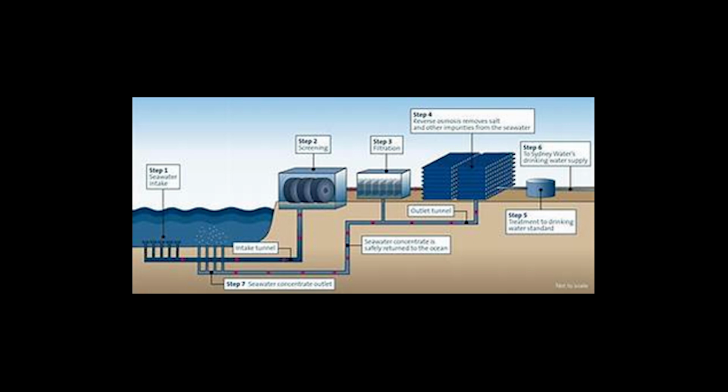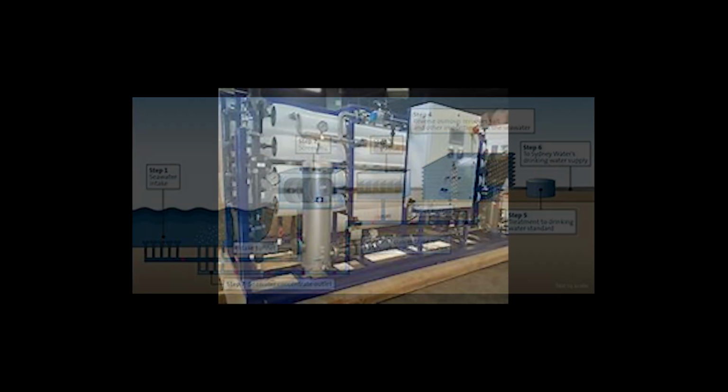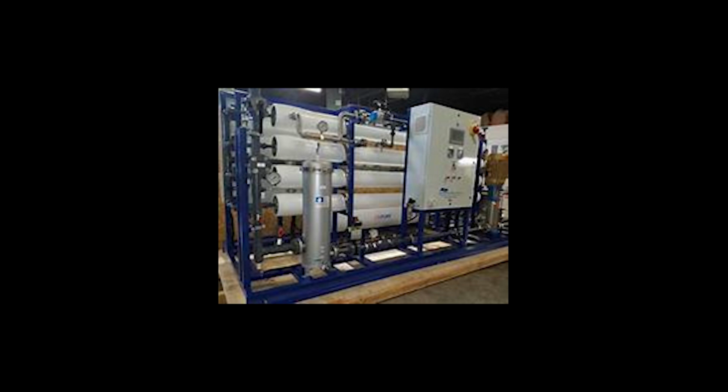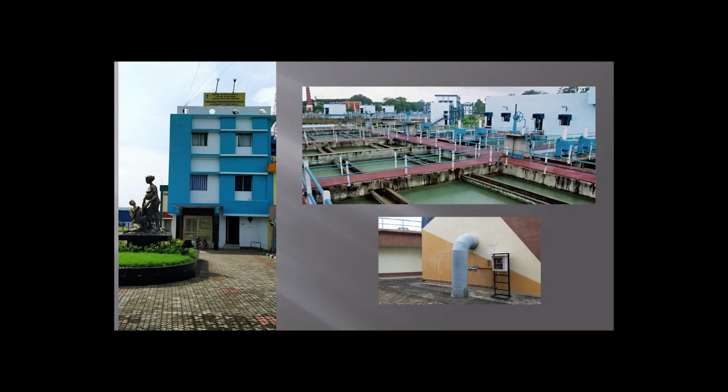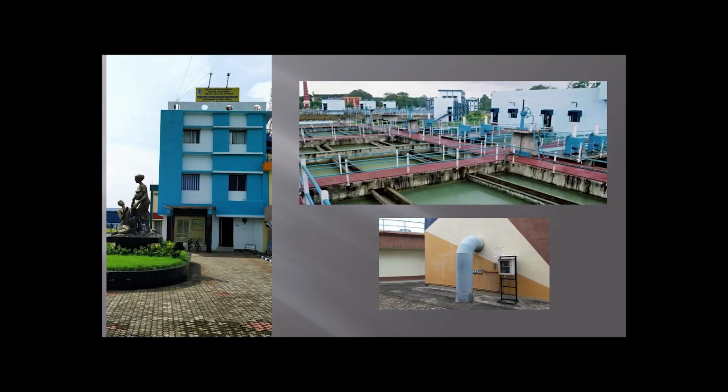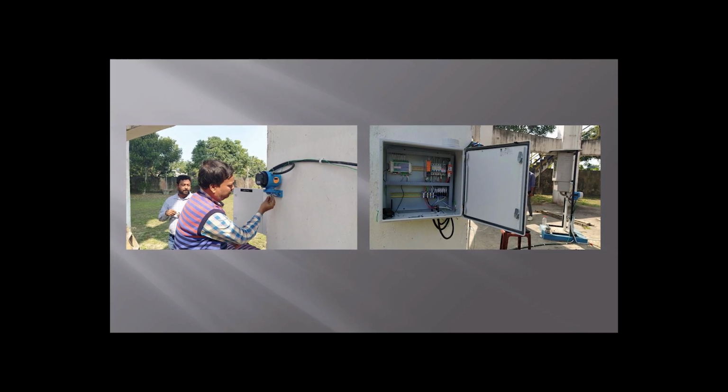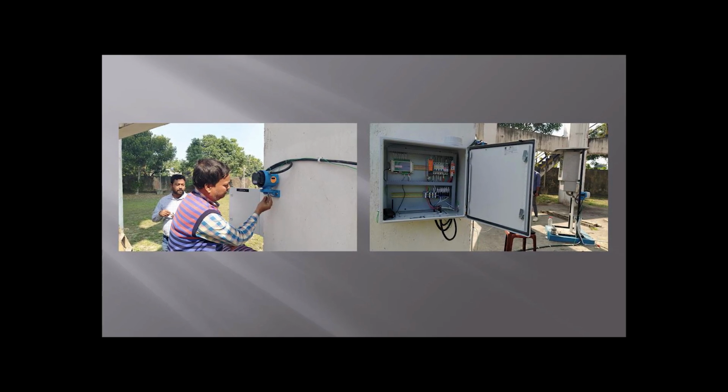There are many solutions to get rid of salinity effect. One easy solution to mitigate this issue or reduce salinity effect is to draw water during non-tidal period where there is no or less saline water in the river. Hence, there is a requirement of monitoring, rather I should say real-time monitoring, of salinity parameter in the river. Based on the monitoring, salinity forecasting or salinity prediction can be done through hydrological modeling, though this modeling is not the topic today.